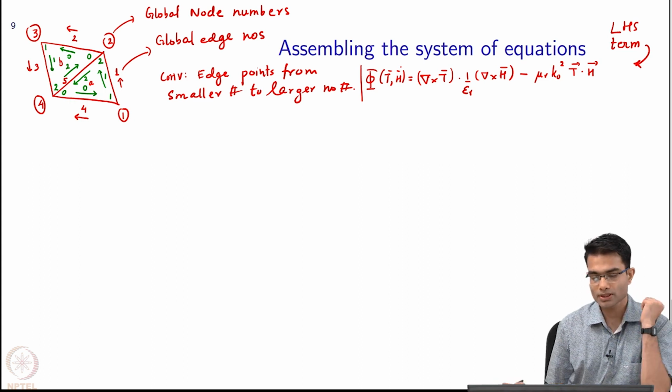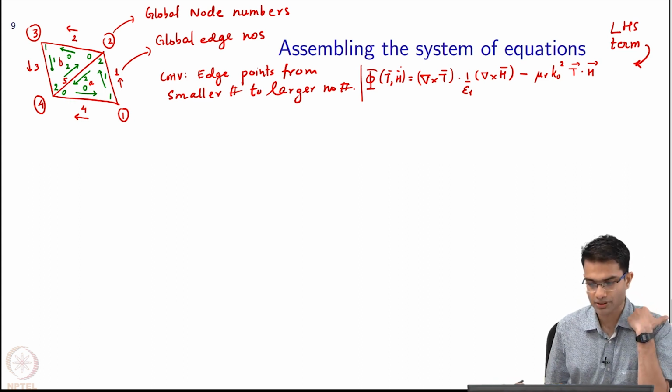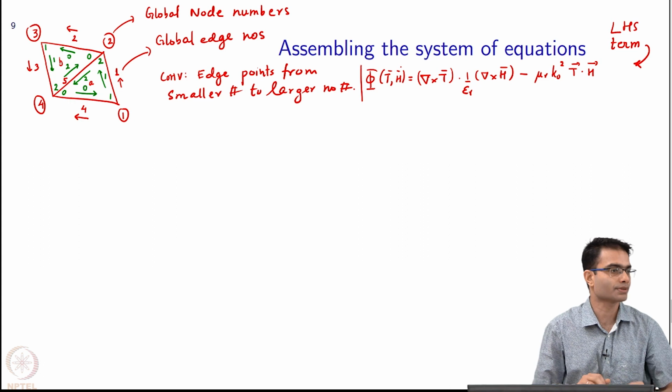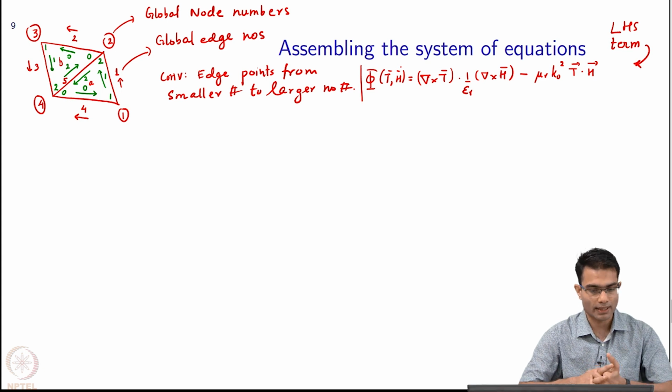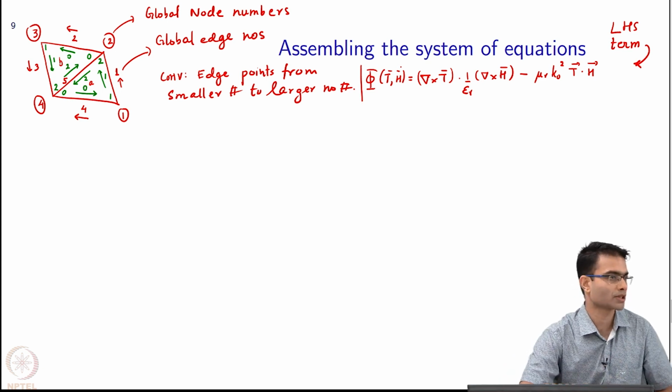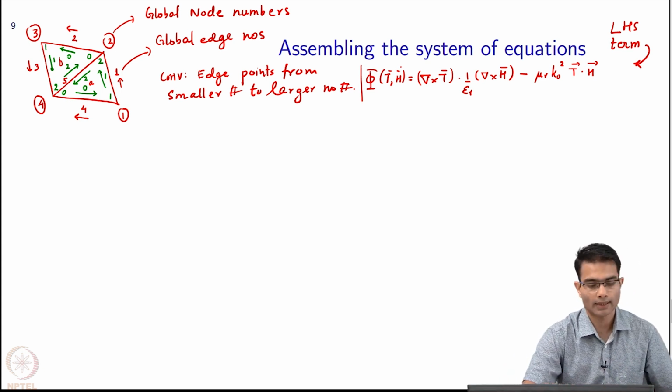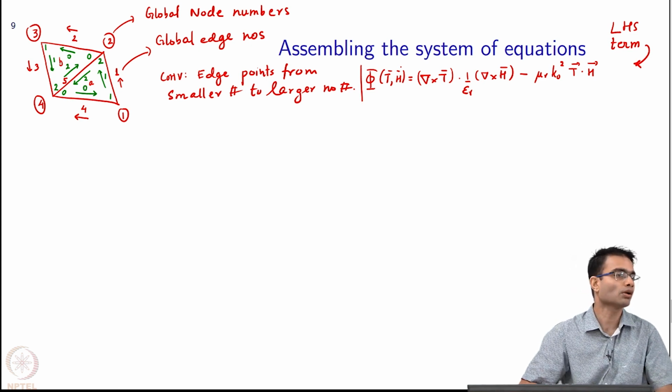So, what is the FEM procedure to get a system of equations? Take one t. So, supposing this very simplistic example of just 2 elements, supposing my mesh was just made out of 2 elements, then how many edges do I have in total? 5 edges, right?